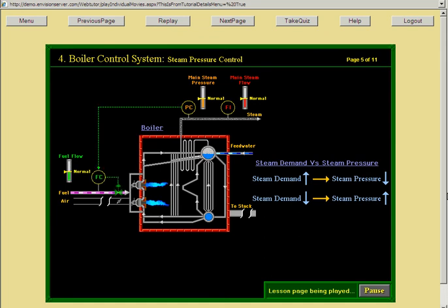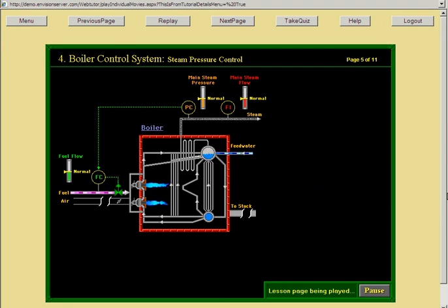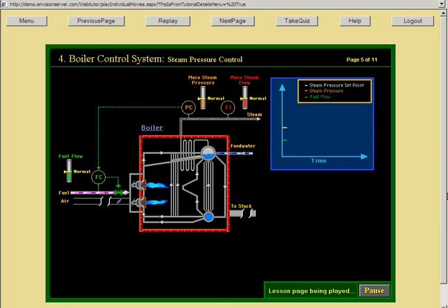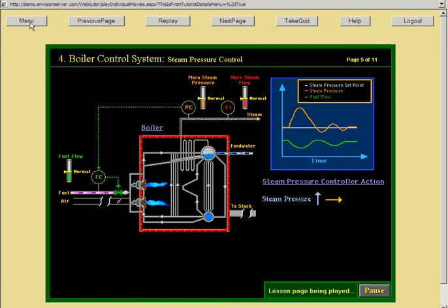The steam pressure is controlled by manipulating the amount of fuel burnt. As the steam pressure increases, the fuel flow is reduced to produce less steam, and the steam pressure is brought back to the design value. Similarly, when the steam pressure decreases...